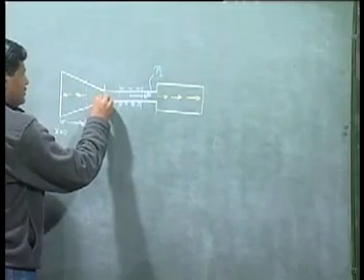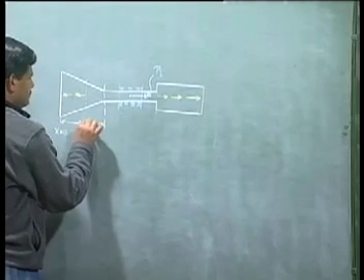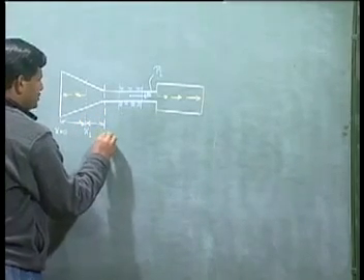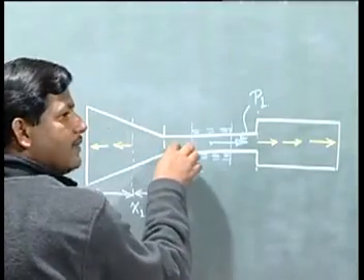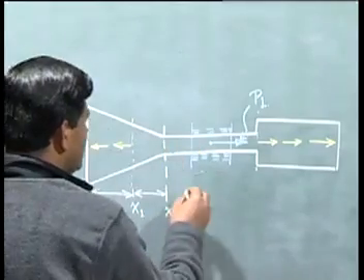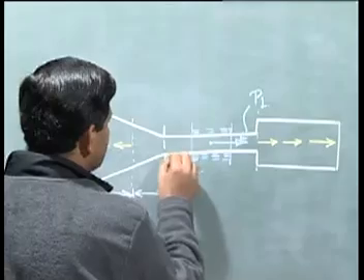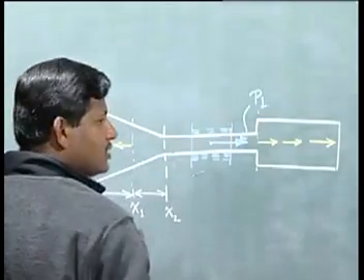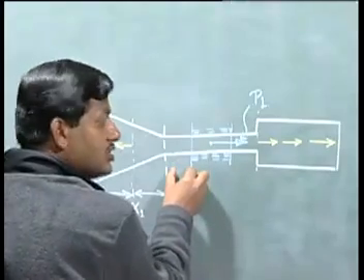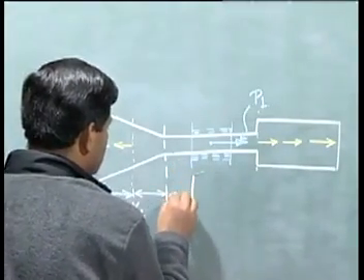The next subdomain will be this one, which will go up to the point x2. Here the material is one type, but the cross sectional area is changing, so I have to honor that. The third subdomain is this part, with a constant cross section but no distributed spring. So this will become my third subdomain.